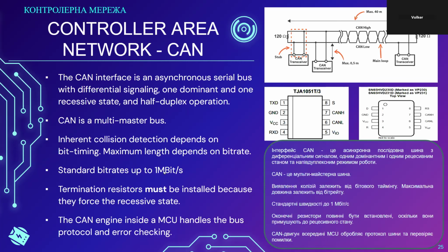The other CAN controller that you see on the right is a CAN controller for 3.3 volts. Those are also not common. Most of the time, CAN controllers are intended for 5-volt operation. Again, those are just chips that I'm pointing out that you can use as a starting point for a search for the ideal CAN transceiver, sorry, not controller, CAN transceiver, that best fits your application.